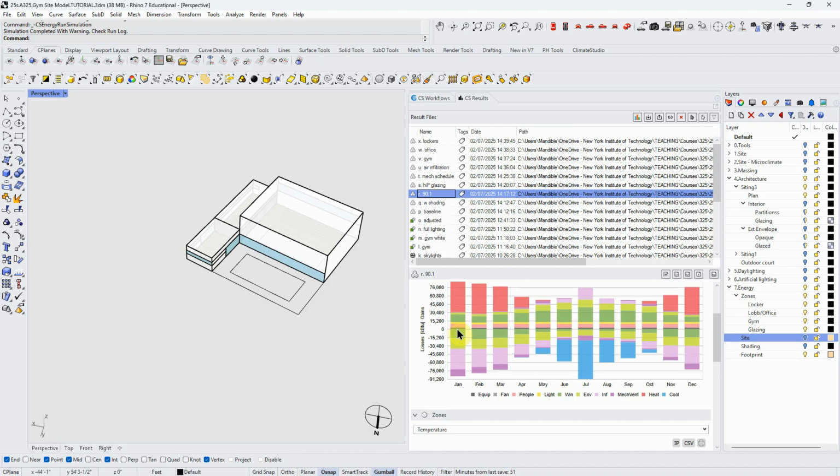This is called an energy balance chart. We have every month is balanced, and so we have the same amount of gains as losses, and we have those divided into different components from our building. Like lighting is that little yellow strip. The windows are this darker green. The envelope's the lighter green. And so I can look and see things that I would like to try to improve.